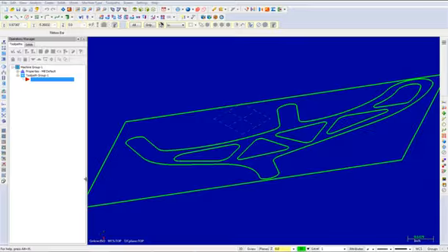In order to bring in this part, you will need to go to www.emastercam.com/files/. Once you have done this, your part will appear as shown. The plane in which the part was created is not one of the standard planes. In order to machine the part, you will have to rotate it to match the way in which it is fixtured on the machine. In the next step, you will create the view in which the part was brought in.